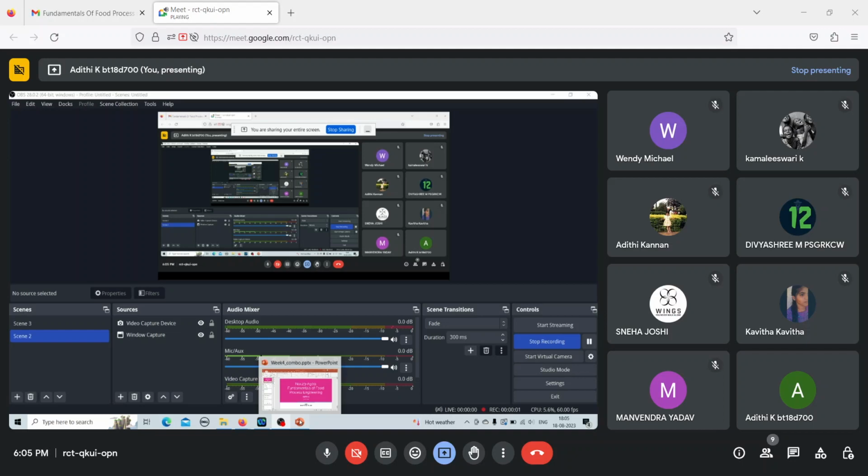So we have a total mass balance and we have a mass balance for solids. With these two equations and with the given numerical values, we can solve for the V that is asked in the question. Substituting the values in this equation, we have 120 kg per hour into XF, which is 0.13. L we do not know, so we keep it as it is, and XP is given as 0.38. From this, we can calculate L to be 41.05 kg per hour.